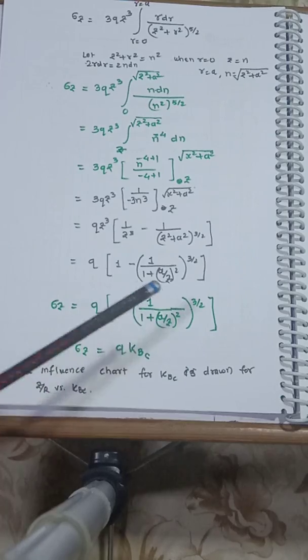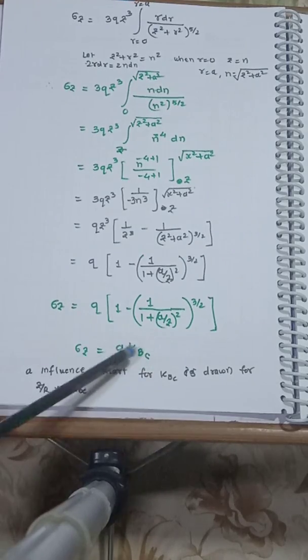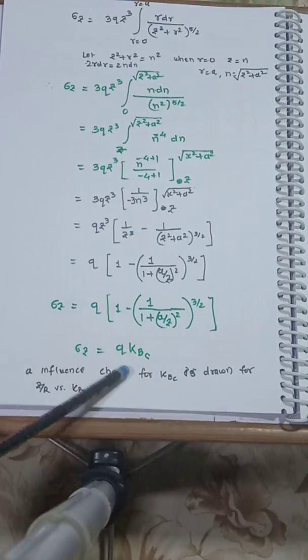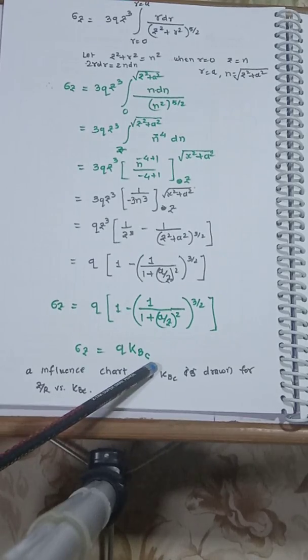A is the maximum radius. Sometimes we also call it the maximum radius R, R1, R2 like this, the maximum radius of the footing or a tank. So you'll find that this is also something like an influence factor, and sigma z is the vertical stress.